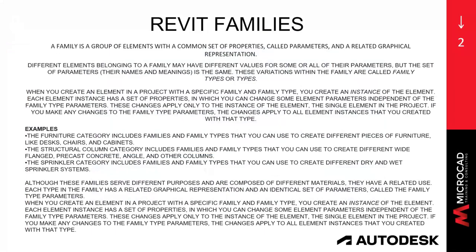Within the families, if I have, for example, a table, and I want to have 3 different sizes of that table, it will make sense to create on that same family different types that will help you keep a reduced family library. They tend to become humongous in companies because you end up wanting to create everything.